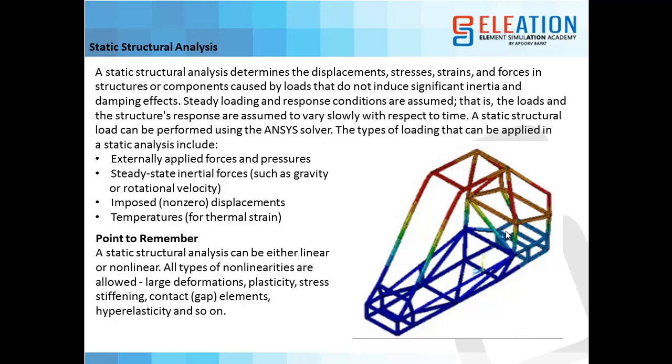Points to remember: a static structural analysis can be either linear or non-linear. All types of non-linearities are allowed: large deformation, plasticity, stress stiffening, contact gap elements, hyperelasticity, and so on. So basically in static analysis, we mainly try to find out the values of stress, strain, displacement in static condition.